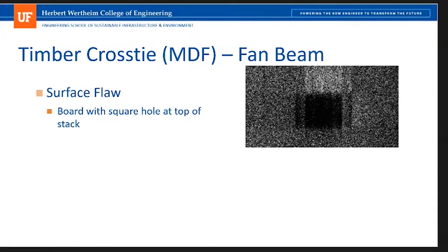That's just due to the nature that there's only a detector on one side of the flaw. So you get some shadowing effects, and that's what you're seeing there. You can eliminate these shadowing effects with either a filter or by putting a detector adjacent to it, and then stitching the images together would allow you to remove that.